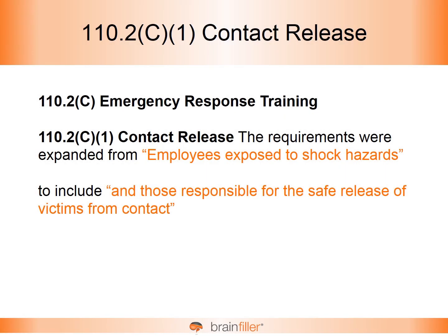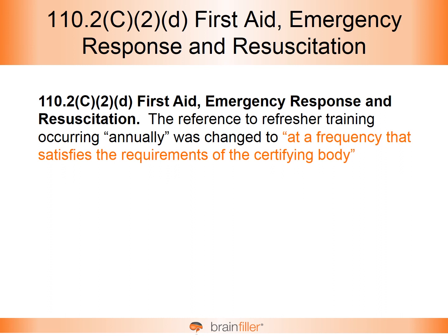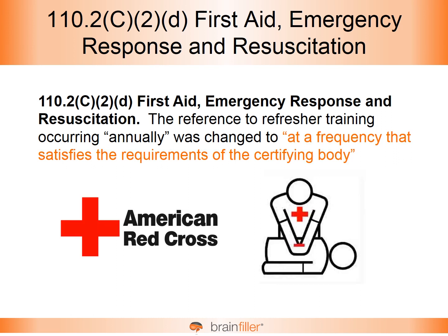Contact release. The requirements were expanded from employees exposed to shock hazard to include those responsible for the safe release of victims from contact. First aid, emergency response, and resuscitation. The 2015 edition stated that the refresher training needs to occur annually. However, this introduced a bit of a contradiction because the American Red Cross has a 2-year certification period for CPR. So this was changed for 2018 to say at a frequency that satisfies the requirements of the certifying body.